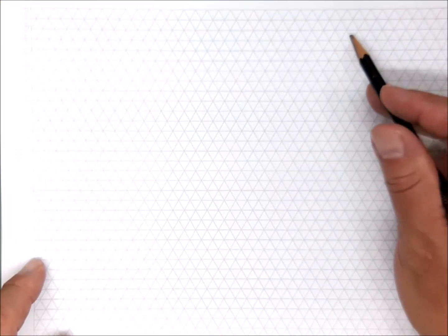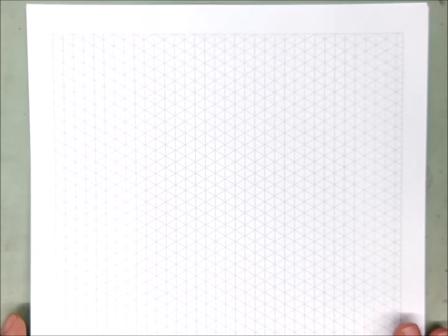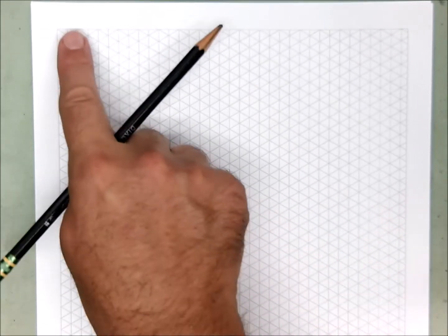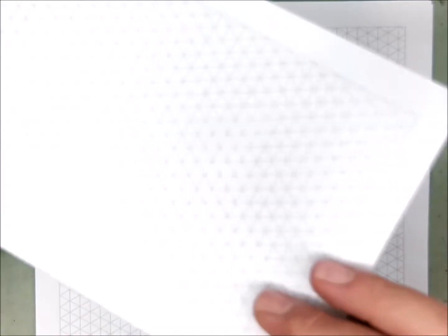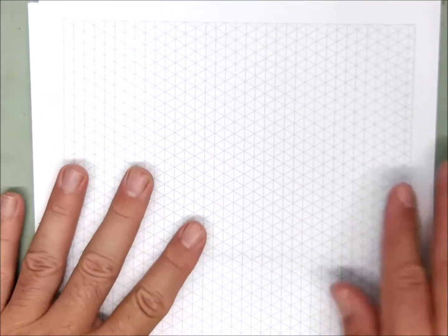Okay, so I'm using my isometric graph paper here, and I am holding it long ways up and down. And that's kind of important because if you hold it the other way, long ways left and right, you're not going to get a 30-degree angle, you're going to get a 60-degree angle. That's definitely not the angle that we want to use for isometric. Okay, so hold it so that the 8.5 dimension is here and the 11 is going up and down. We will fold them in half just like we did before. And that'll give us a more than adequate amount of space to make our isometric sketches in.